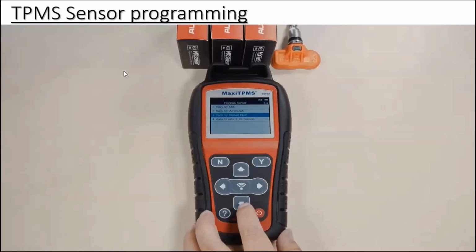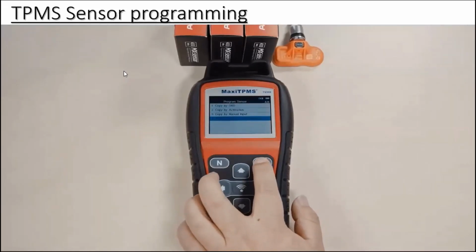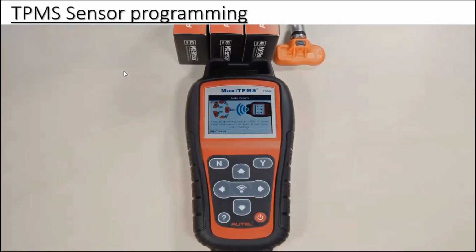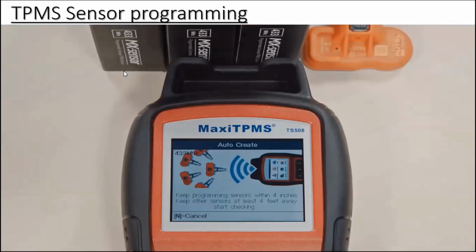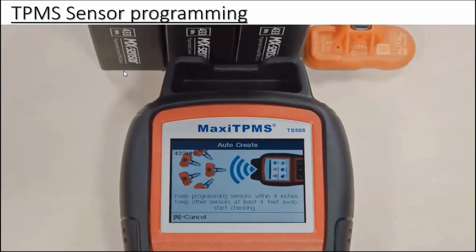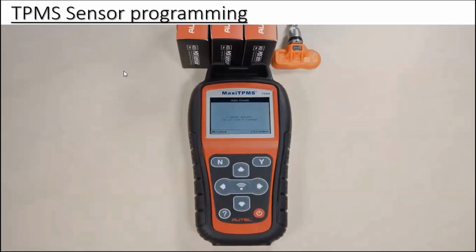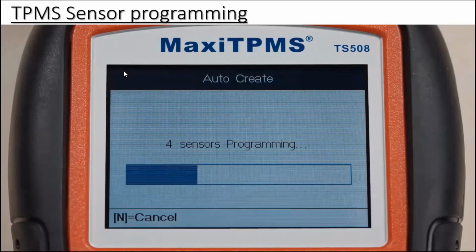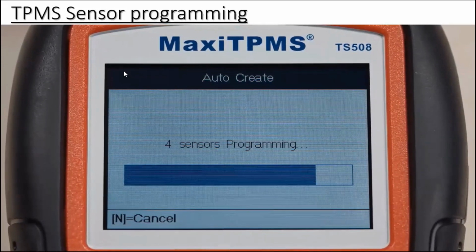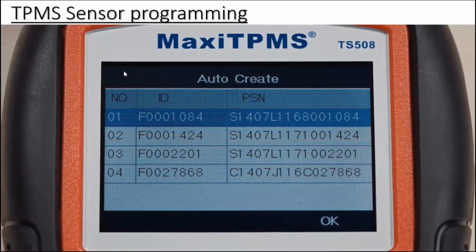Auto Create. Auto Create will generate a new ID randomly for an MX sensor. You can program from 1 to a maximum of 16 sensors at the same time. Put the sensors close to TS508. Keep other sensors away. The tool will automatically detect the sensor. Press Y to confirm. Each sensor will be programmed with a specific sensor ID. Relearn is necessary for Auto Create.